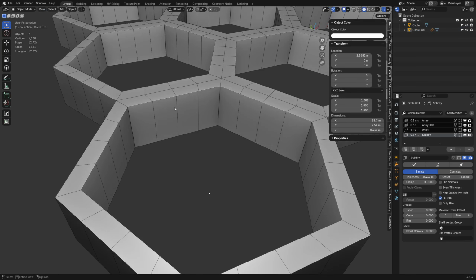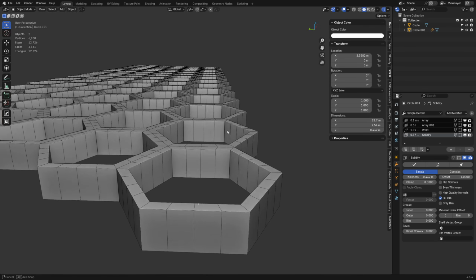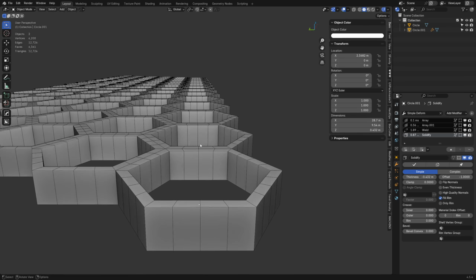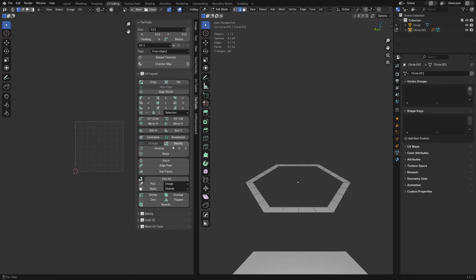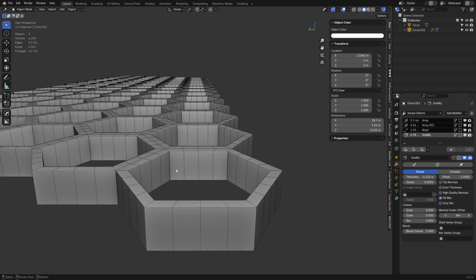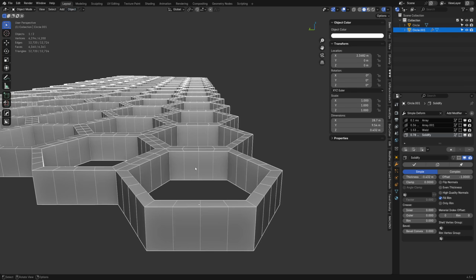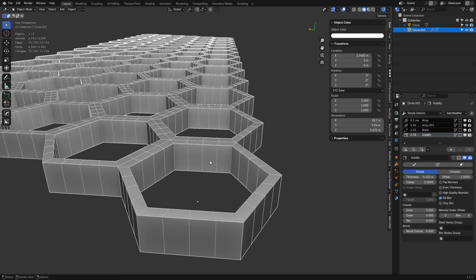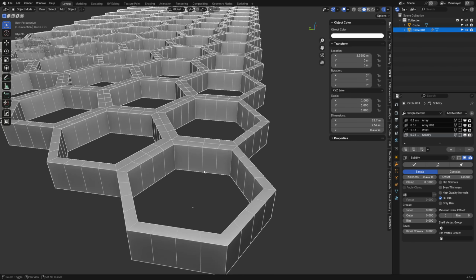How do we unwrap something like this, right? This is pretty challenging if you don't know how to do it. Usually there'd be a seam on the back side, and then these would all taper inwards on the UV map. Unfortunately, Blender has issues a lot of times with all kinds of different features, little nuanced things like this. It's a little bit challenging to do that here in Blender. So a lot of times it's actually better to taper everything when you're creating something like this.